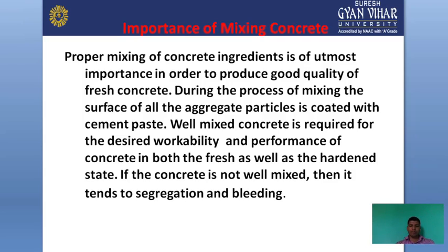During the process of mixing, the surface of all aggregates particles is coated with cement paste. Well mixed concrete is required for the desired workability and performance of concrete in both fresh as well as hardened state. If the concrete is not well mixed, then it tends to segregation and bleeding.